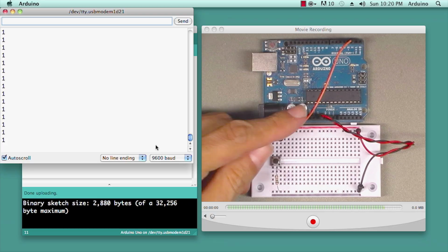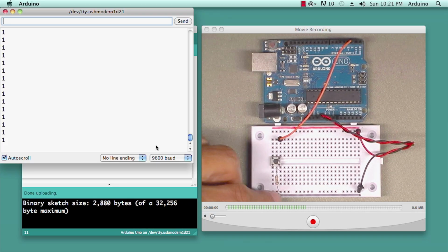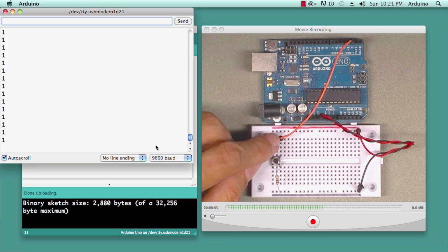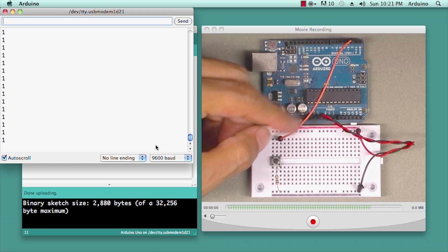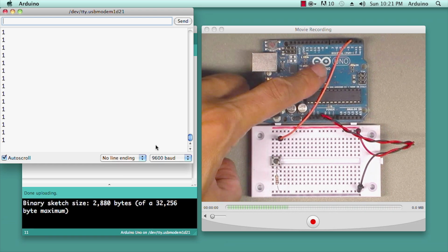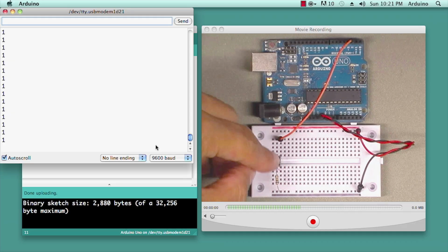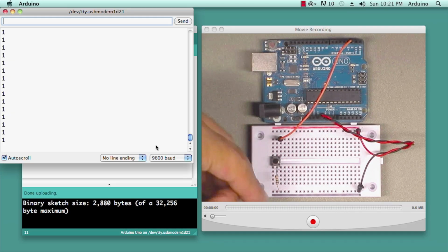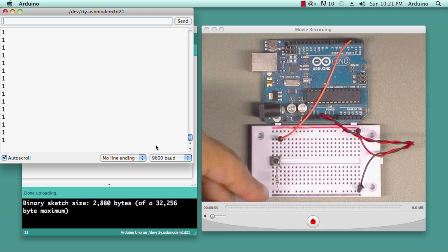So this is a path of very high resistance. It goes from ground through the resistor, through the open switch, because the switch does not have to be pushed for this connection to happen, through the signal wire to pin 2. Pin 2 would love to go any other path it could possibly find, but that is currently the only path available to it. So it's going to take the path of least resistance, which in this case is a path with a lot of resistance. But we're going to change that in a moment.